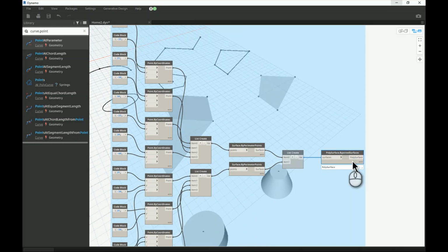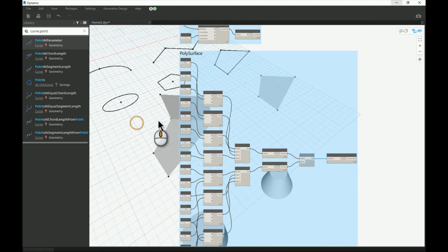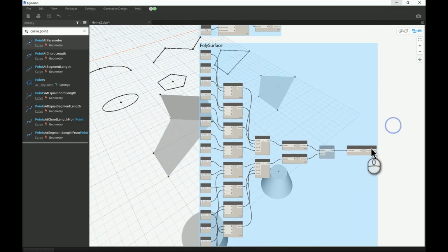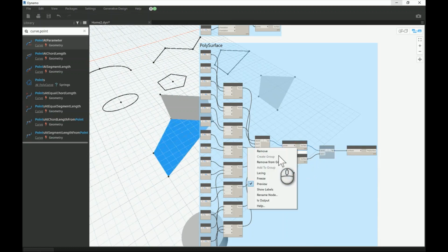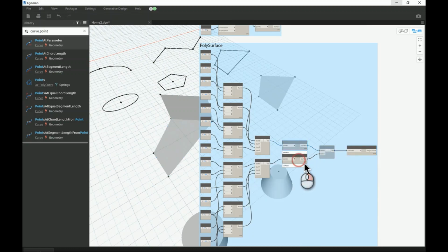Now that's a nice issue that always happens when you click on something and it doesn't show up. Remember that if it's a complicated geometry built from two previous geometries, like this one, you have to turn this off, because this is just the combination of both of those. So sometimes when you select it, you don't see it. Now when I select it, it will be blue.